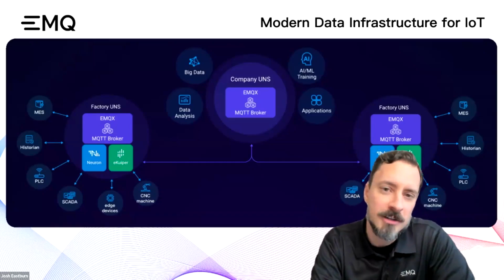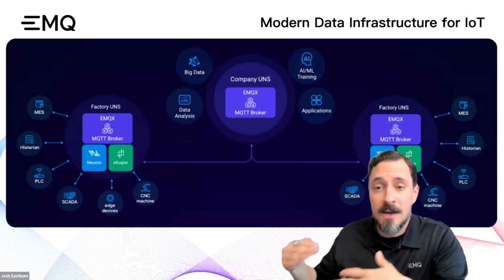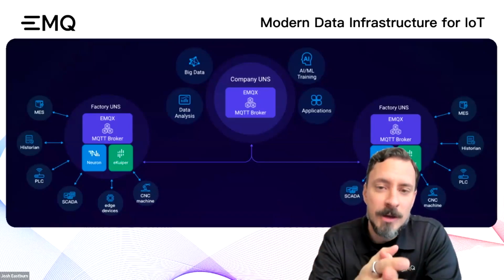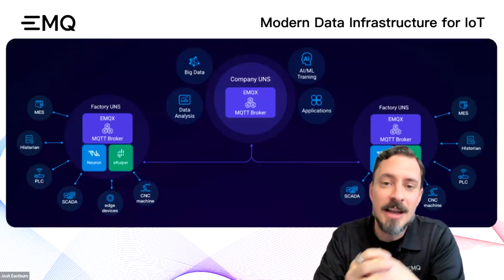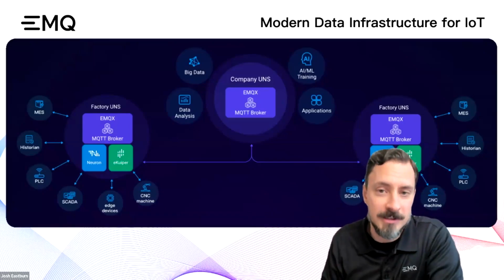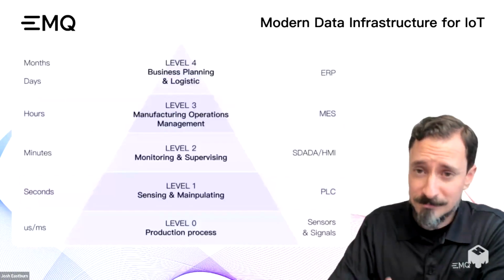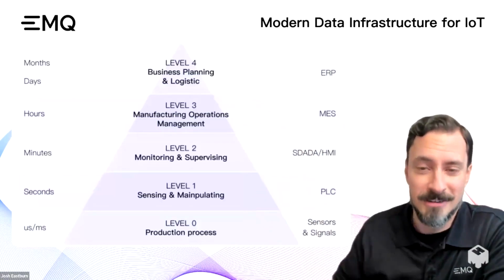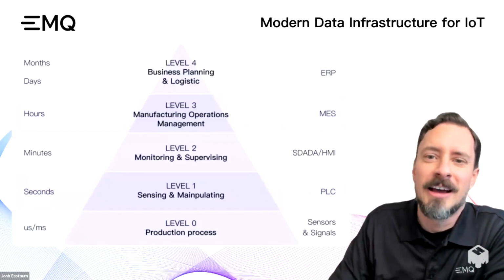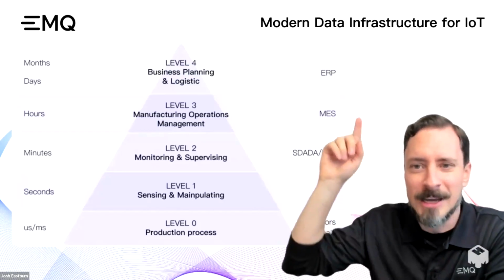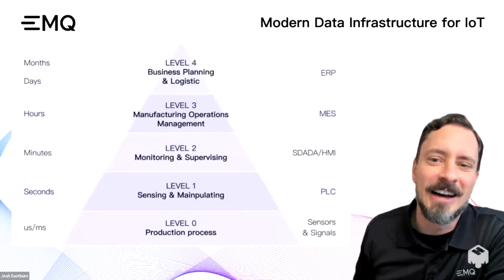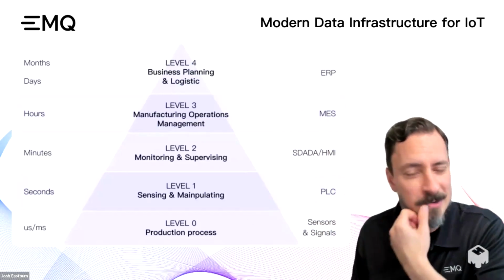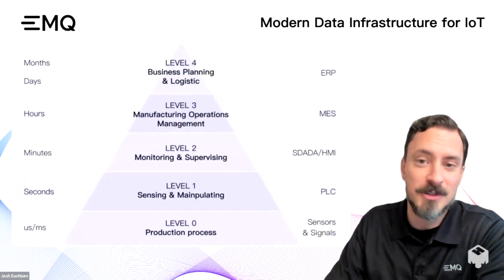And this is becoming a new architecture for IIoT, where instead of having this very stratified architecture, we're designing a common space, a common hub where all of that data feeds in and can be consumed by every other client, right? If we go back here in this architecture, data moves up pretty easily, but it's kind of designed not to move down, right? For security reasons, right? People who are doing the enterprise planning up at the top, we don't want them sending control signals down to this layer where they might affect the process. Okay, so cybersecurity is still a concern that doesn't go away.